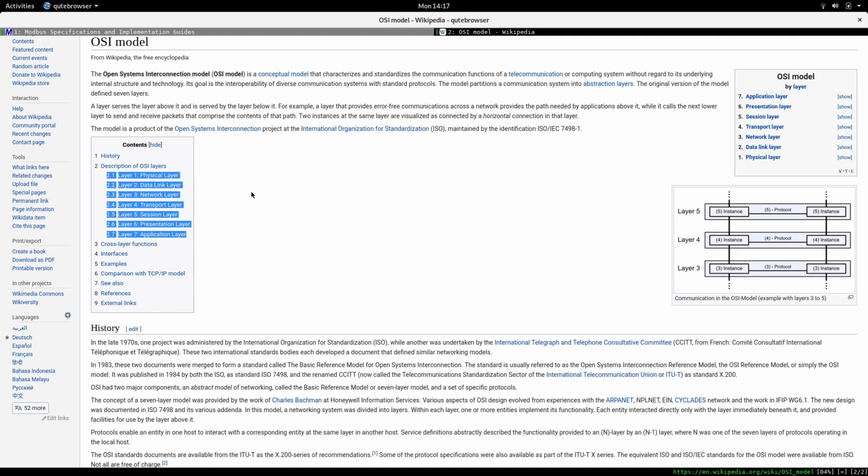Now we've talked about RS232 and RS485, which would both be physical layer protocols. They define the communications medium, which in the case of RS232 is just a copper line, and in the case of RS485 is a twisted pair. But it also defines the electrical signals. So in the case of RS485, it's a differential signal between the two lines. One line is positive to the other, or vice versa, and that transmits a 0 and a 1. That's a physical layer protocol.